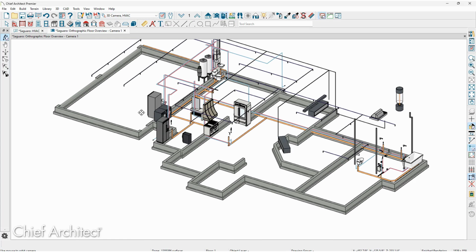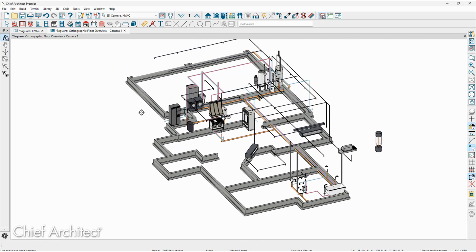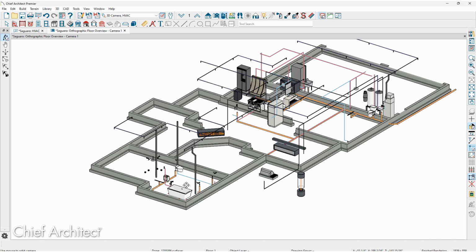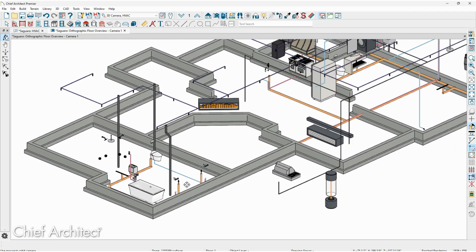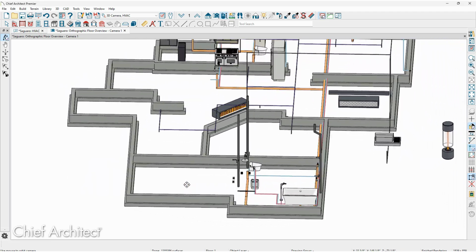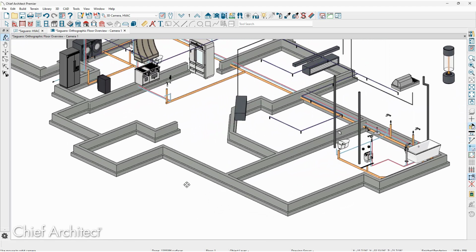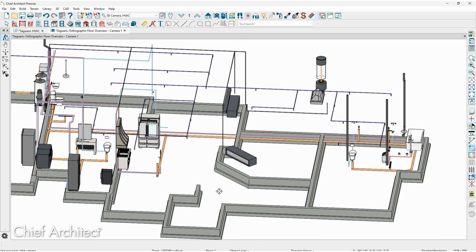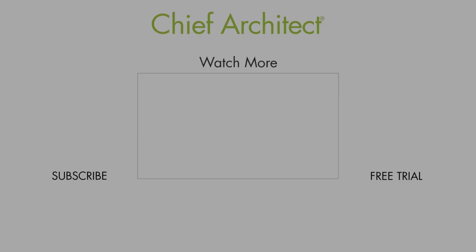And now you can see the isometric view that was created. This is a floor overview, and you can see that bathroom area that we were working on. As you rotate around, you can see the wastewater lines are inside the foundation wall. It makes it easy if you're going to create an isometric view to set this up as a layer set, and that way you can use the molding polylines specifically for such things as a plumbing diagram.